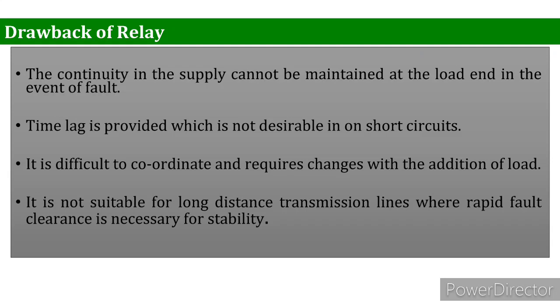And lastly, the relay has difficulties in distinguishing between fault currents at one point or another when fault impedances between these points are small. So we can say it has poor discrimination quality.